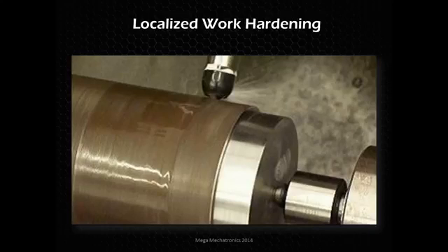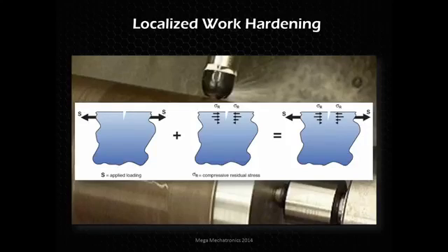And then touching on compressive stresses, why those are important. If we look on the very left, a material, let's say it has a little crack in there, but if there are compressive stresses, everything's trying to push things together. Those compressive stresses are pushing that crack back together. So when you apply a load to split that crack open, there's actually compressive stress countering that, and that's what gives it fatigue strength when you shot peen a part or roller burnish it.